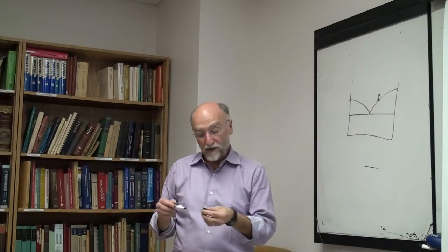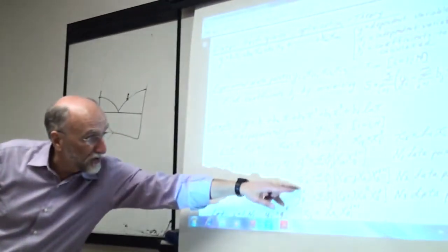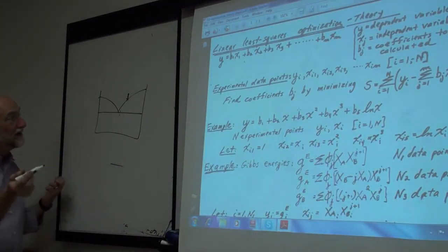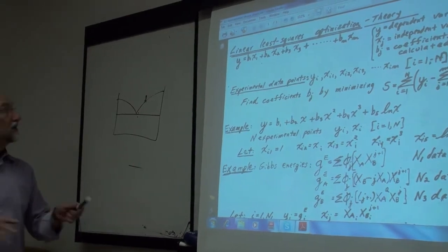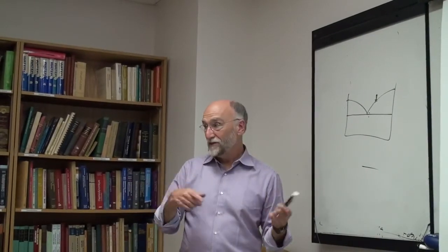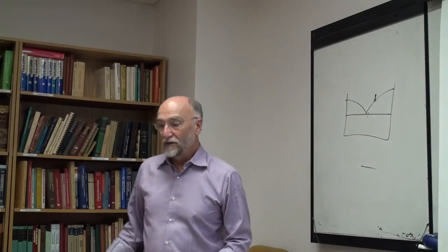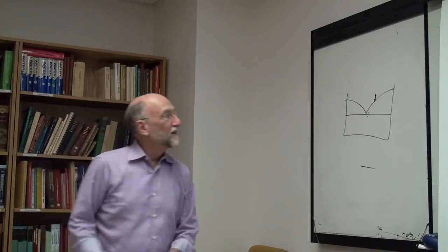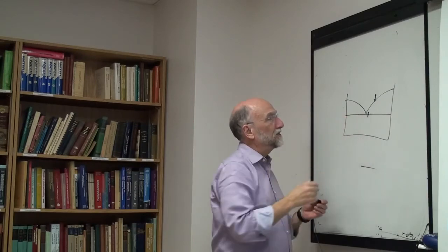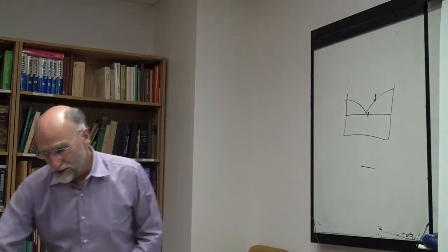And you can calculate anything there. Here you've actually got to fit the actual equations for the partial and integral properties. If you're using this technique, you can have FactStage calculate eutectic composition. You can have FactStage calculate vapor pressure. You can have FactStage calculate all sorts of things. Okay, and then you can minimize the total deviation between whatever you measured and whatever FactStage calculated. On the other hand, the weighting of these things can be real hell, because it looks good, but you end up giving a huge weight to certain points, and then the other points are just kind of forgotten.